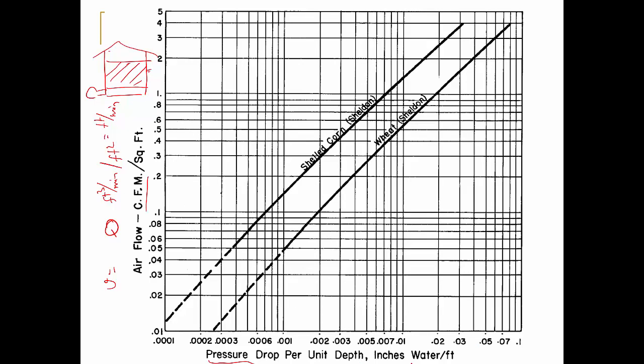So in a grain bin, if the grain is stored at 10 feet, you divide the total pressure drop by 10 feet. What they found is that the depth is linearly related to the pressure drop. So they normalized by that, giving inches of water per foot. And then they had these logarithmic axes, and they generated almost a linear curve on the log axis.